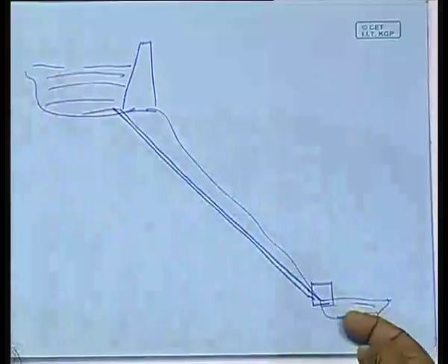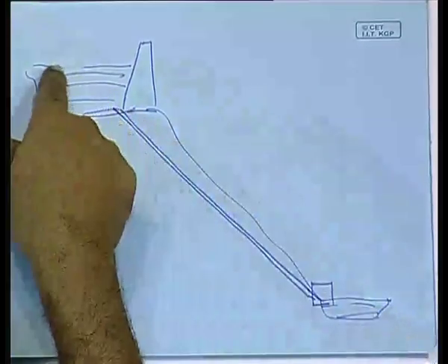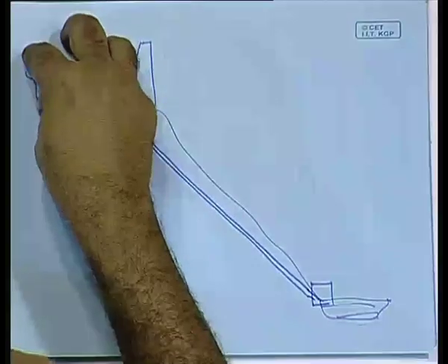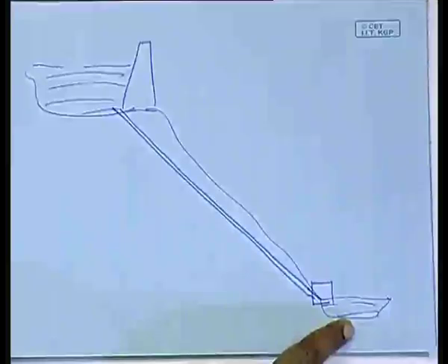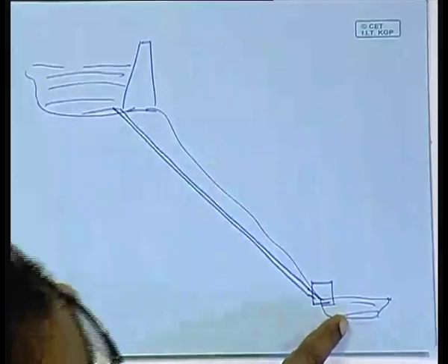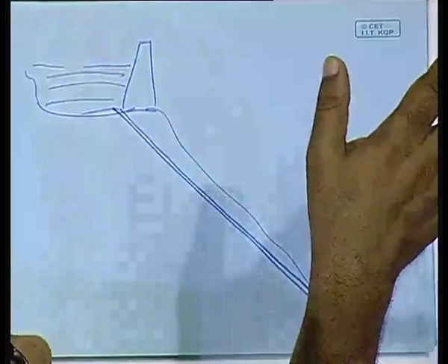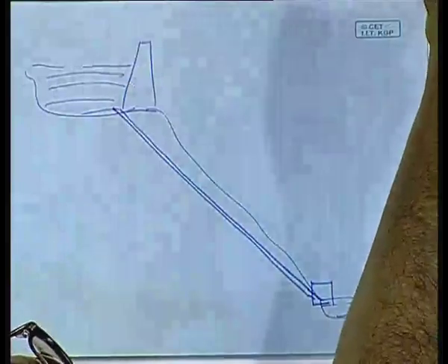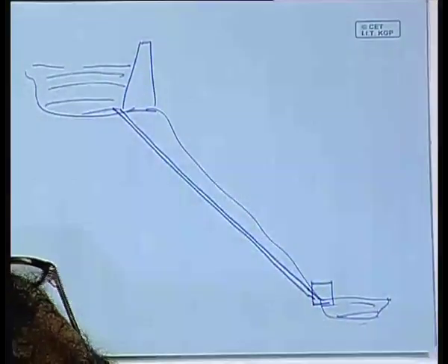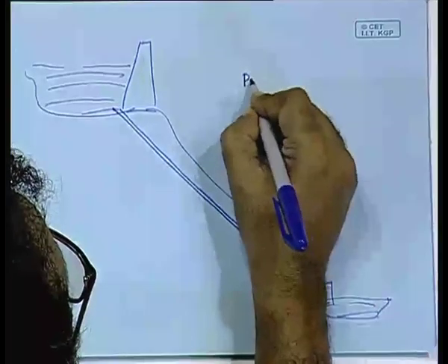Okay. So use the surplus power to pump water up there, so that additional amount of water is available when you really need it. And during peak hours, allow that water to come down. Thereby, what you achieve is that on the thermal power plant, the load is level. You have used that amount of power that was excess during the night to pump up water, and this water is available to fill the gap during the peak hours. This is called pumped storage.